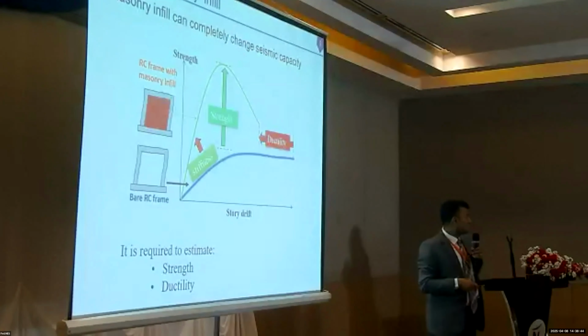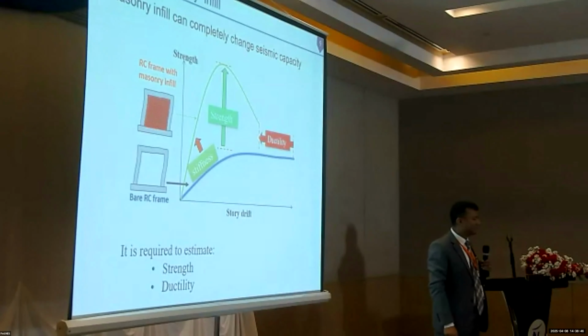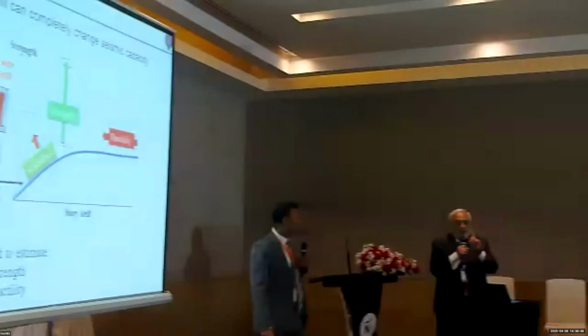I'm sorry to intervene, I would not recommend that. The reason is that the walls are non-structural and we tend to change them. Sometimes you punch a window, sometimes you punch a door, sometimes you remove the wall, and you cannot put a writing on the wall that this wall is not supposed to be removed. So that is why the strength is there. It's kind of a reserve strength.